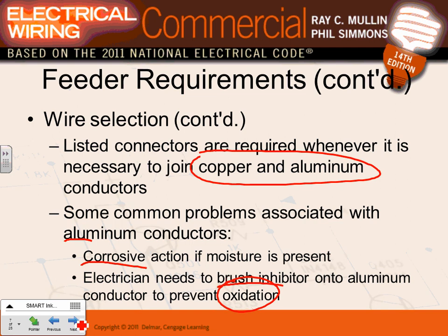That's all. You just have to put your facility on a maintenance program. So every year you have to go to the lugs and detect the heat of the lugs. If they're hot, you're going to torque them, or you shut down for maintenance and retorque all your switchgear and your panels. Done. If you do that, then you're not going to have any problem with aluminum.